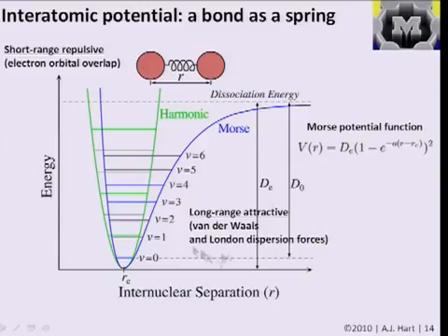And this results from longer range attractive intermolecular forces, which we'll call van der Waals forces and dispersion forces, and we'll see the origin and definition of those in a couple lectures. But the origin is not important here. What I want to say is that we can use, for example, a potential function, a function which basically tells us the curve of energy versus separation, and we can take the derivative of this, or a couple derivatives of it, and by linearizing this function around this static separation, we can say, well, here's about the stiffness of the material, or about the stiffness of the bond.